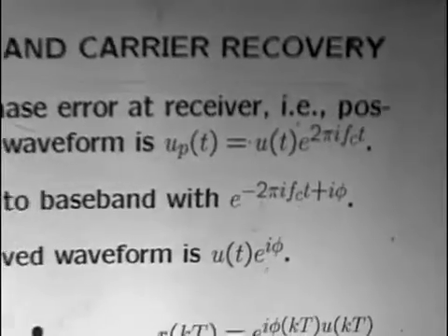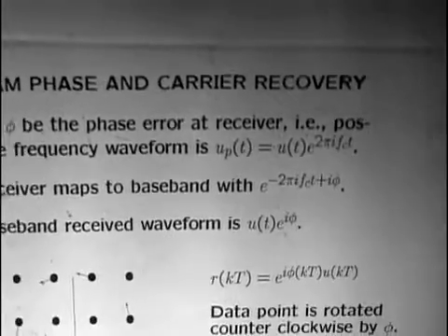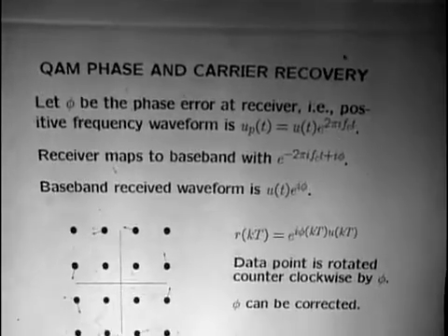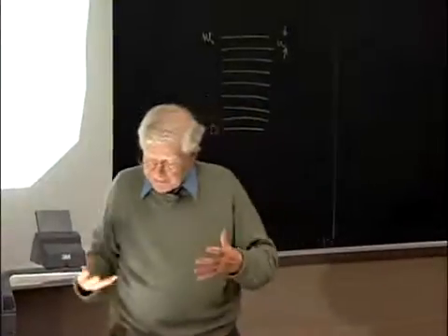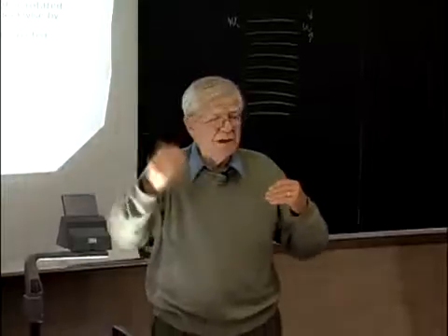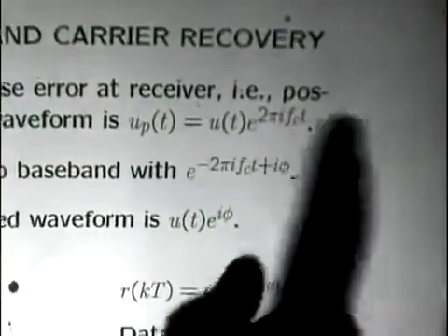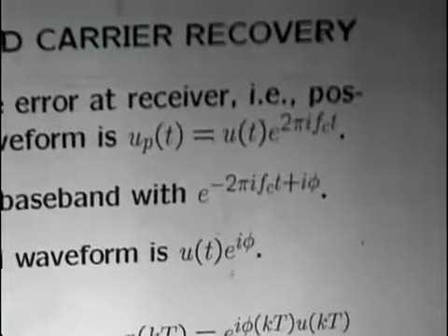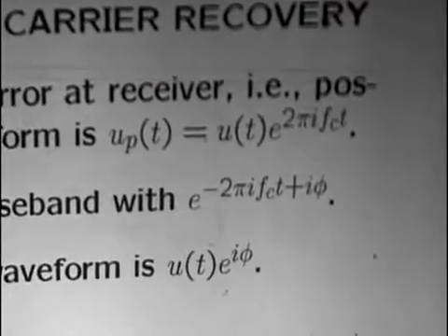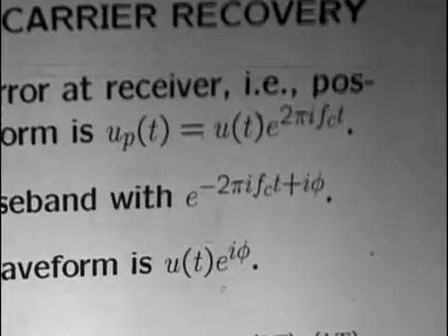If you look at it in terms of complex signals, it's a very easy problem, but it's most easy when you look at it in terms of just what's going on at positive frequencies. Okay, so the thing we're doing here is when we modulate, we're taking u of t, we multiply by e to the 2 pi i fct. What happened to any arbitrary phase that we have in the transmitter? Well, nothing happens to it. We just define time in such a way that it's not there.